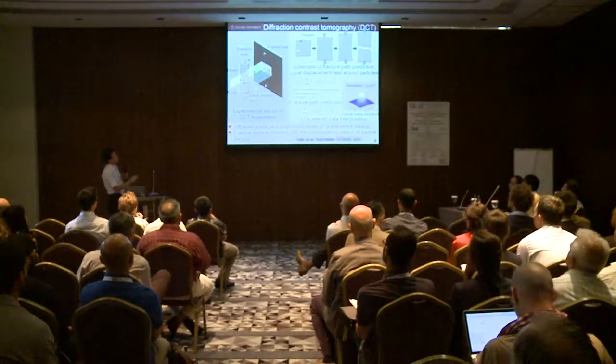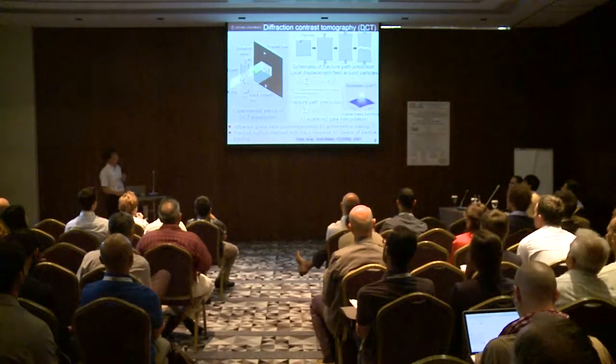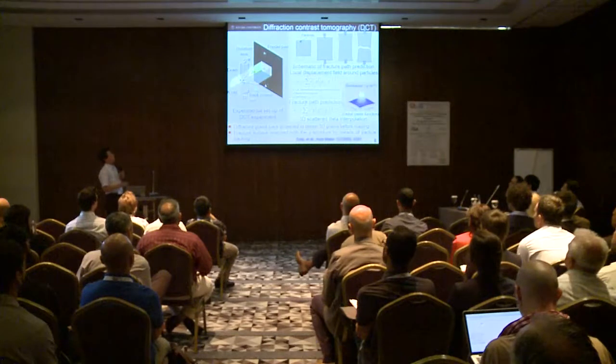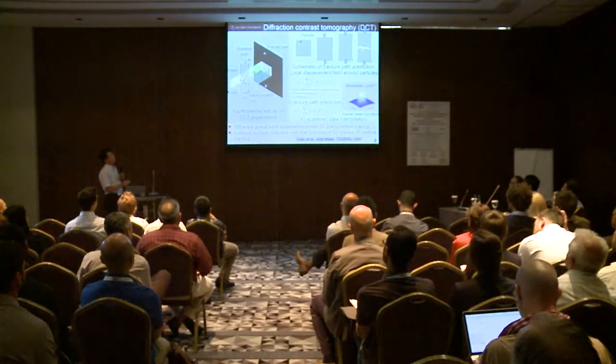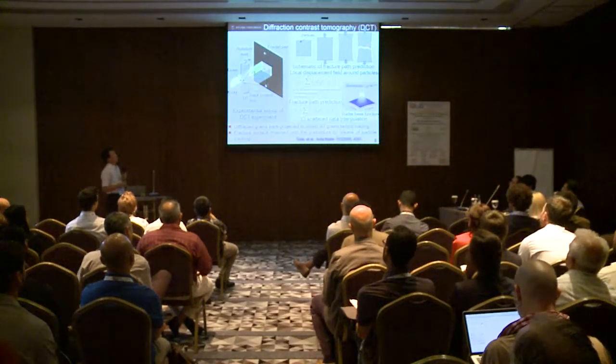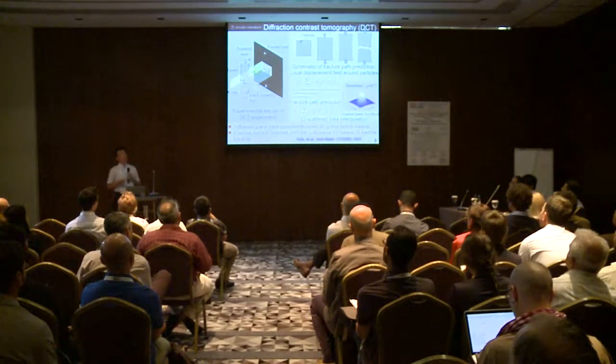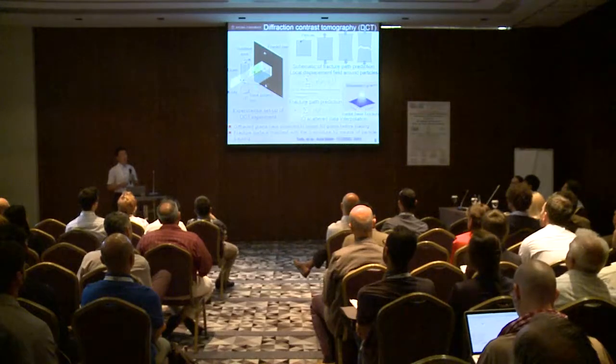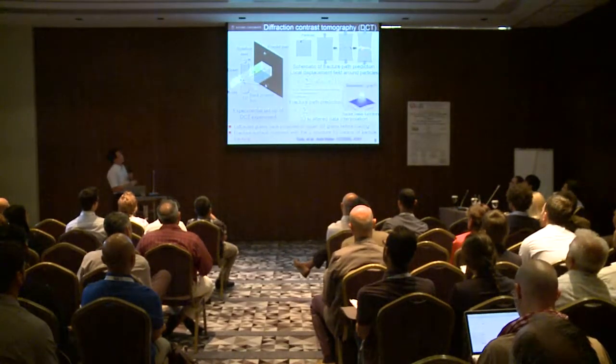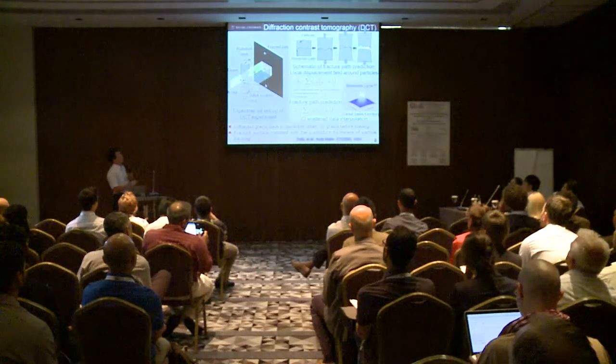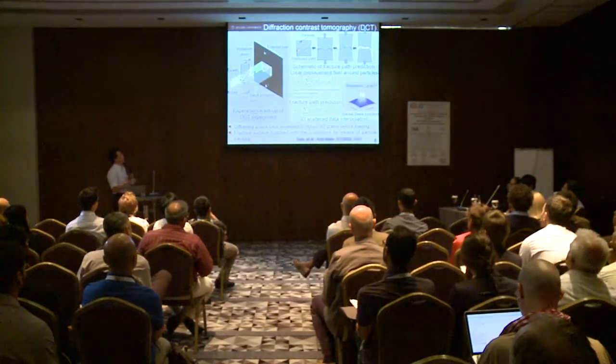And what we do is we have a series of tomographic images, and then we extract the position coordinates of fracture surface patterns so that we can reproduce the configuration of the fracture surface very accurately. Then we track the physical displacement of this fracture surface backward in time from the fracture surface to the initial unloaded state to see the correlation between crystallographic structure and fracture surface.